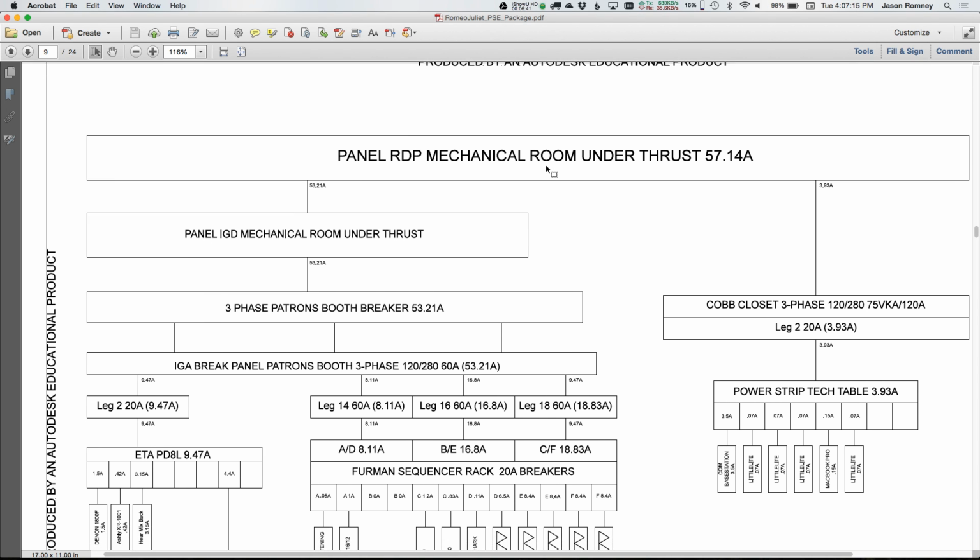But what you want to do is make sure that you're finding all of the different points where a breaker could be that you would be able to access in the building if the worst happens. Because the power company will help you sort out the power up until it gets into your building, and then from there, it's up to you. Once it leaves the building, then it's their problem. But if it's inside the building, it's your problem. So you need to know where all the possible failure points are. You need to know where those exist.